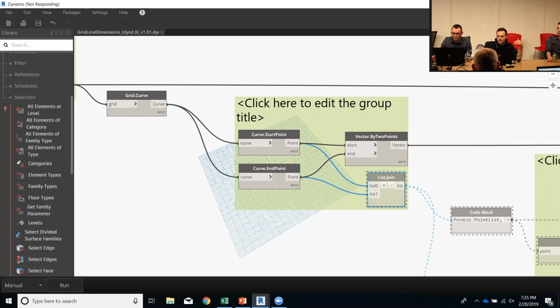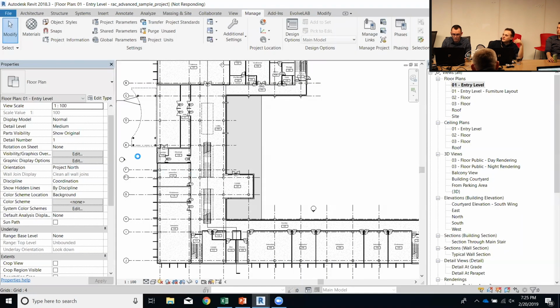And that's thinking a little bit, maybe running into an issue or two. But again, these grid lines, we know that that's where the start point and end point of our string needs to behave. So we have to identify somewhere along column line J and go all the way up to A, and then somewhere along column line 1 and go all the way out to 8 or 9, whatever it is. So how do we start to extract those information points from our grid lines?